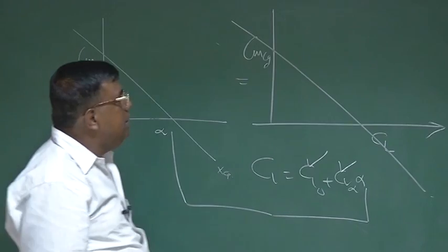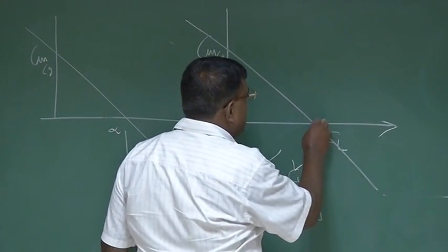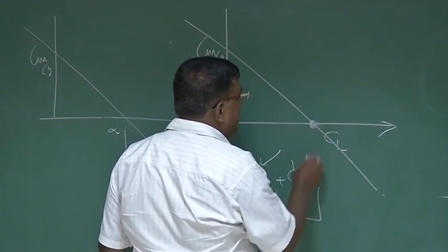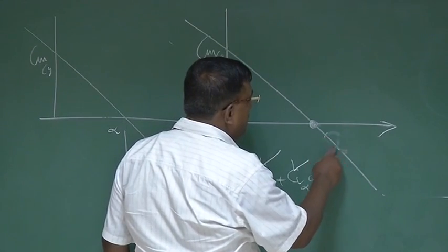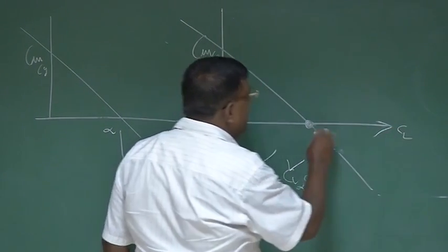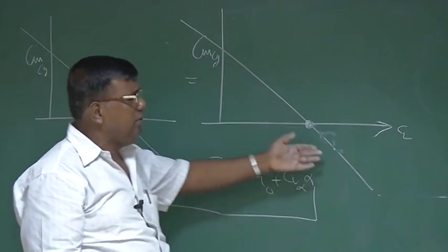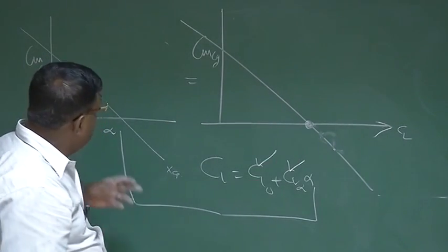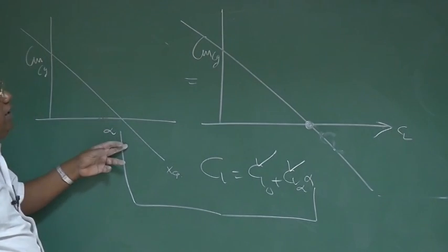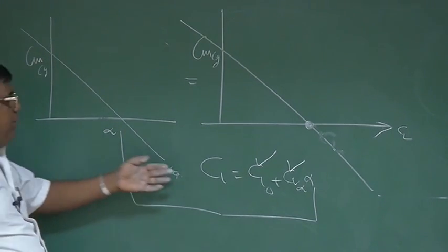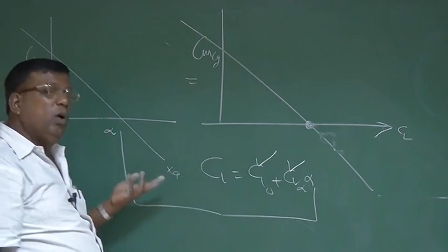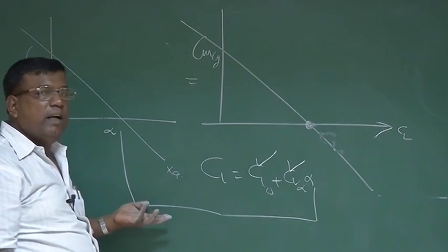Now our question is, let us check the trim point, the equilibrium point, whether this aircraft is statically stable or not. We know it has to be stable, the slope is negative, but we know only that the Cm versus alpha slope is negative. But because alpha and Cl are related like this, by number the slope has to be negative.